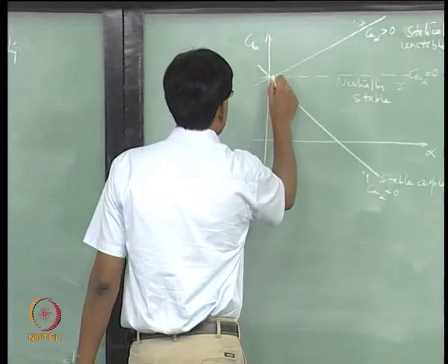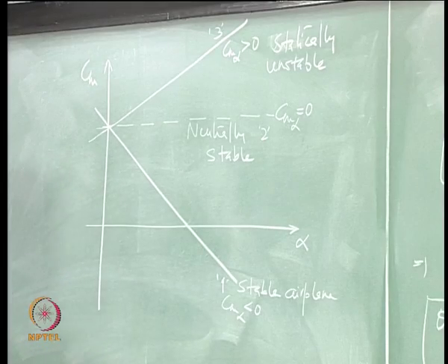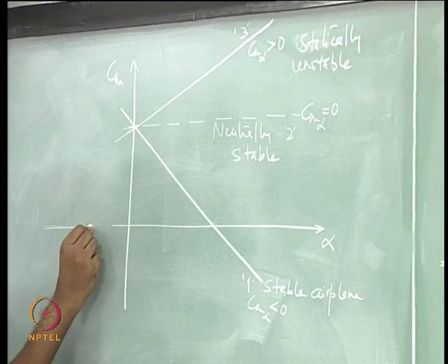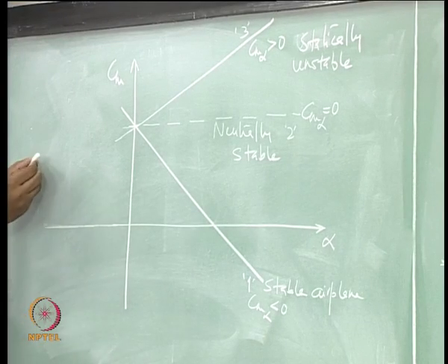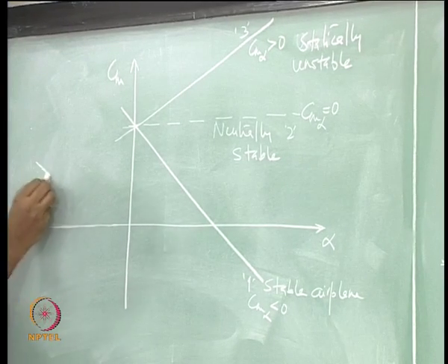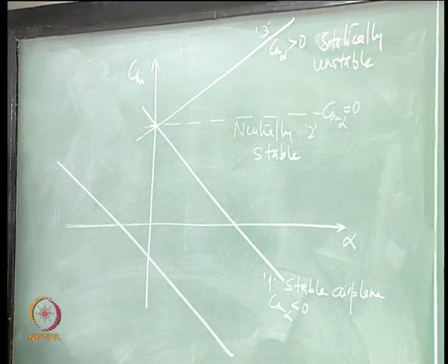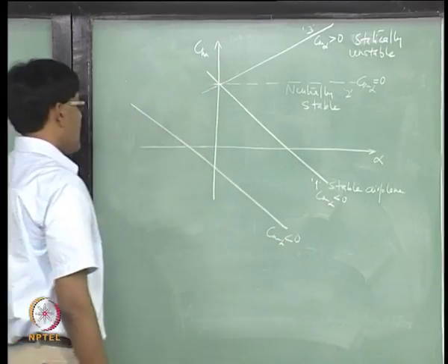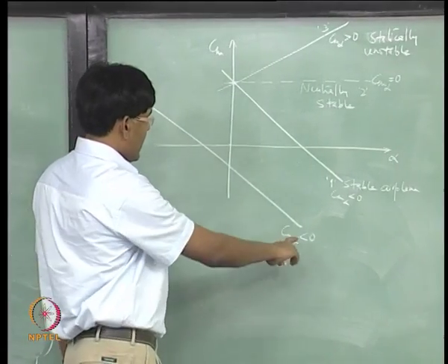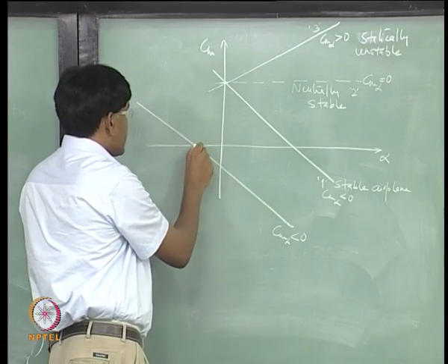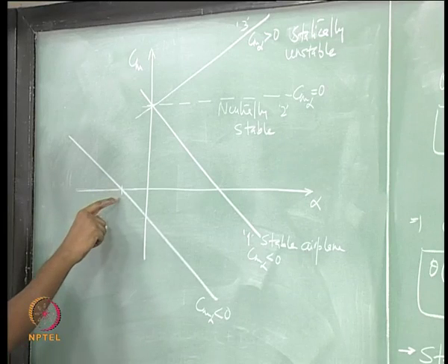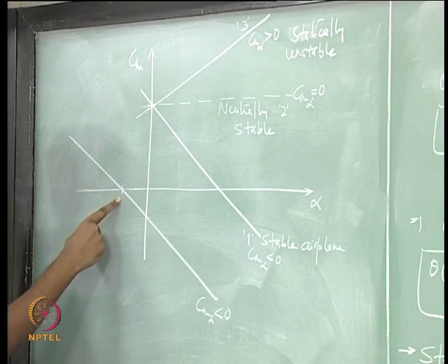The other thing that the aircraft designer has to keep in mind is not only about satisfying just this criterion. You can satisfy this criterion even when you have a Cm versus alpha profile like this. So, here clearly you have Cm alpha less than 0, but what is happening in this case is this curve is cutting the alpha axis at a negative angle of attack, right.